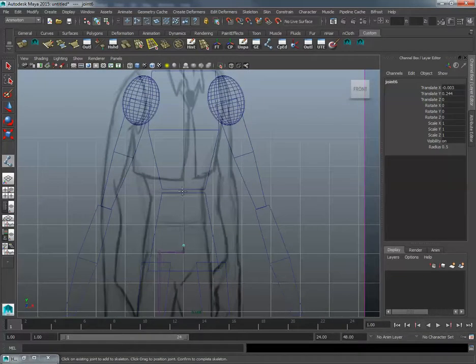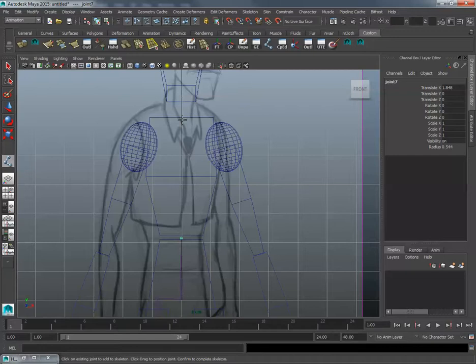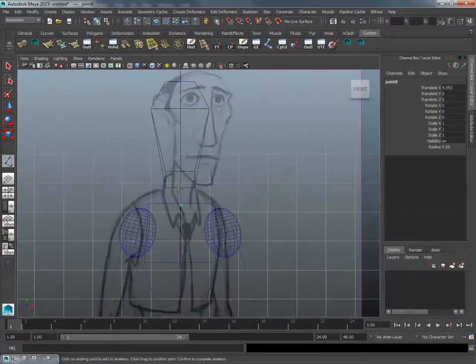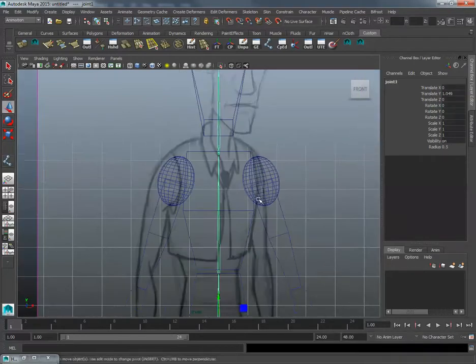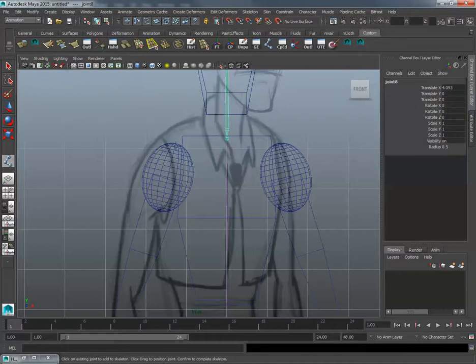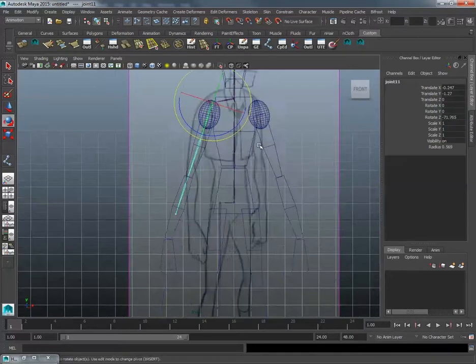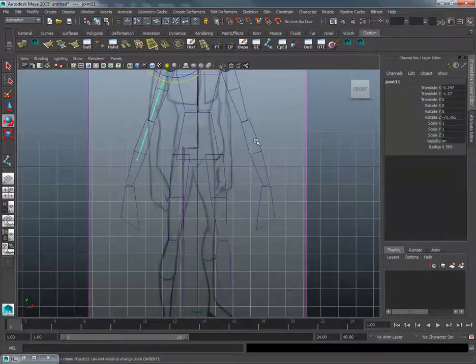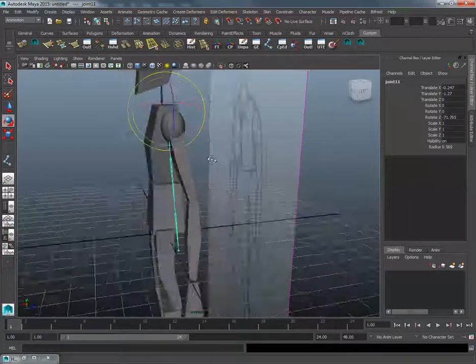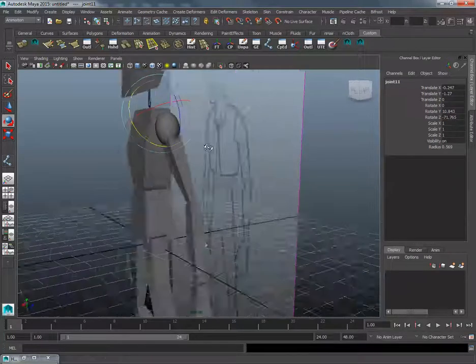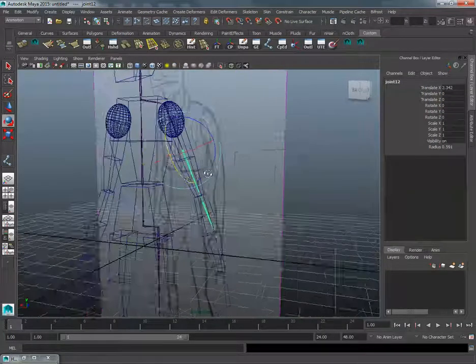Then there's the spine that I'm creating there through the middle, which will go to the head. Again, pressing Enter and G, and then there's the torso, collarbone, and there. Just roughly going to create this as a straight line. Usually I try and make these, I hold down shift, which gives me straight lines, and then after I've done that, I rotate them into place. And they're not always going to be correct. So what you can do is, holding down shift creates nice straight bone lines and can save problems with your IK chains.